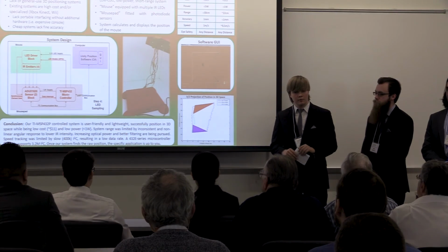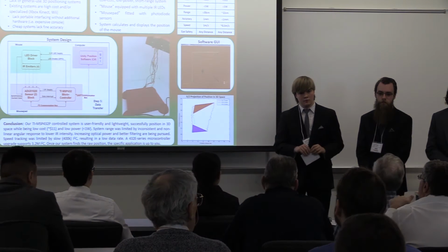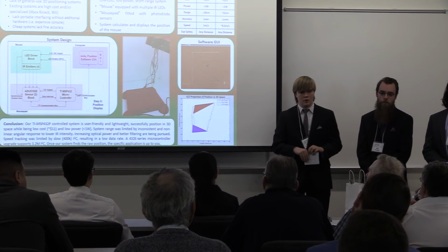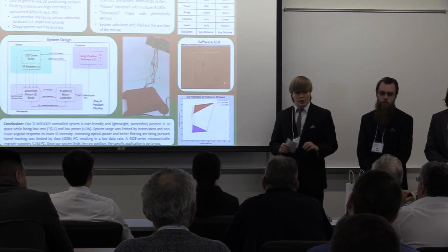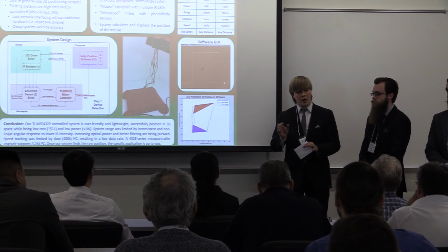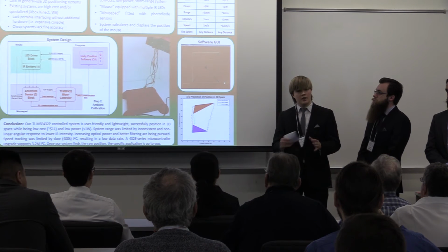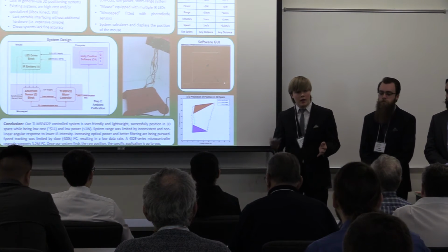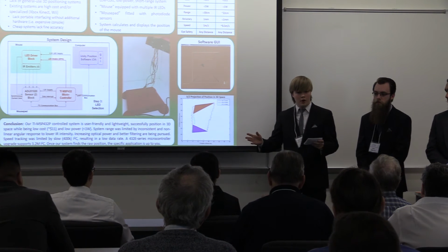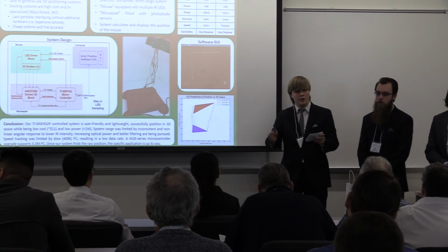Any questions? Yeah, usually in light systems, your ambient light just kills you. I mean, that's one of your biggest problems. What did you guys do about the ambient light? So the sensors, their quantum efficiency is a very narrow band of IR, which is what our LEDs fall under. And in addition to that, the sensor has a calibration procedure where it takes the values that are output from the angle measurements, and you can tone those down repeatedly using offsets.